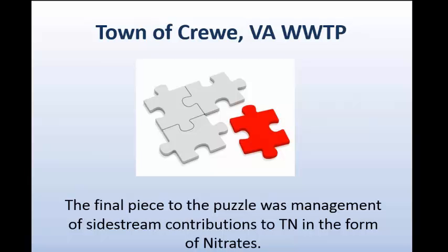Aerobic digestion is the biological process where the solids are held and aerated without putting any additional food source to them. In the presence of the oxygen, the microbes will stabilize the sludge and reduce the volume of the sludge that you ultimately have to dispose of. During the digestion process, because the mass of the microorganisms is being reduced, when you let that settle, you have clear water at the top. We were seeing these spikes when we were decanting, which is allowing the sludge to settle and then drawing that clean water off the top.